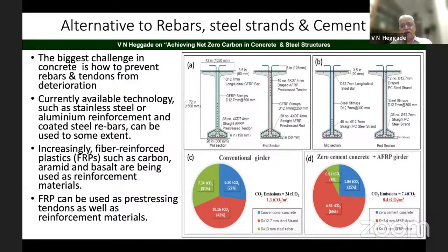It's like a tension bar, and also the FRP bars are there, which can be used for the construction. But unless a lot of research is done, those bars can't be bent at the site the way we want and used. Presently, it has to be ordered. It is order specific. That's the reason that technology has to be changed.